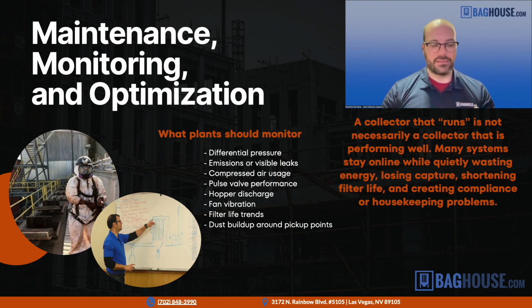Also, though, things like not having the dust collector settings correct. All of these kinds of things affect performance greatly elsewhere in the plant. So if you have a dust collector where you see a lot of dust forming at the pickups, or it's just dusty in your plant, you have to look at the whole system and find out where the problem is. Not often is it just that the baghouse is not doing well, it's often a victim of other things. So being able to diagnose and troubleshoot problems from a systemic perspective is really essential to making sure that you get the best performance out of your systems.